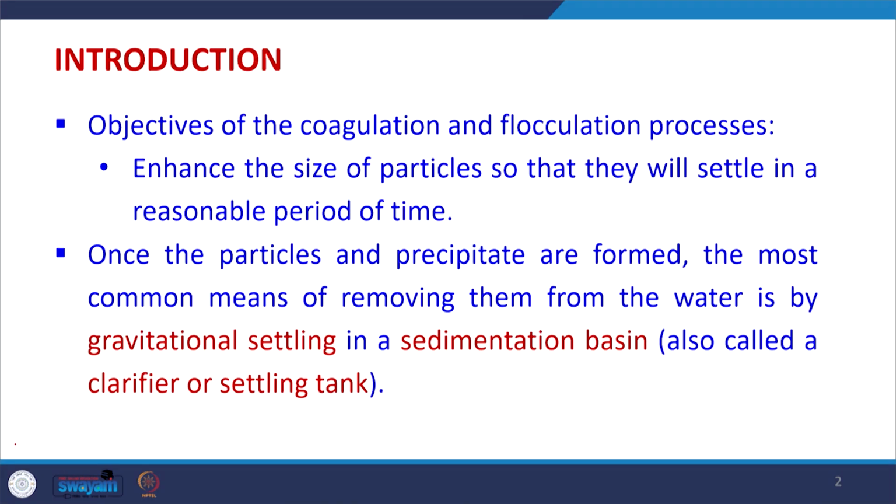Once the particles are settled and precipitates are formed, the most common method of removing them from water is by gravitational settling in a sedimentation basin. So, that is why coagulation, flocculation and sedimentation are generally performed in sequence, and the unit operations are in sequence.